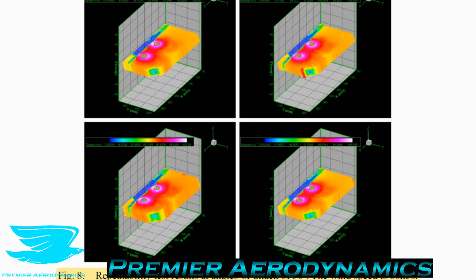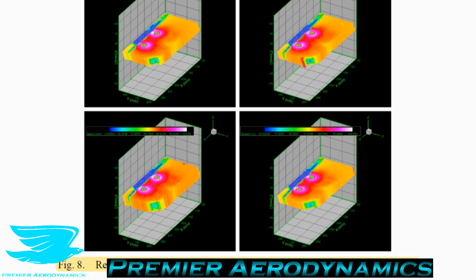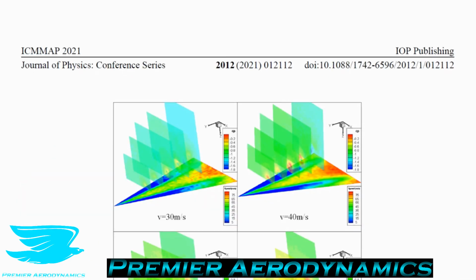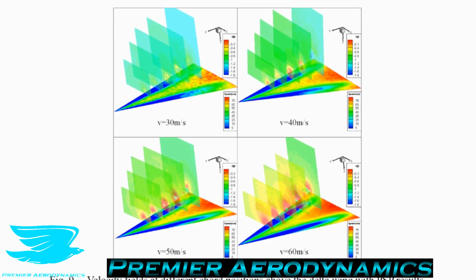One thing that I should note is that with any aerodynamics, there's pretty much always going to be some unsteadiness. That means that when you take 2 different measurements, there's going to be some difference between the 2. Ideally, it should be very little, and that's why we average results often. But there's going to be some minor variations, and that's what we do see here. That's just probably due to which point in the transient cycle they took the pictures at. So these results are very acceptable, and they show that the PIV system was working well.